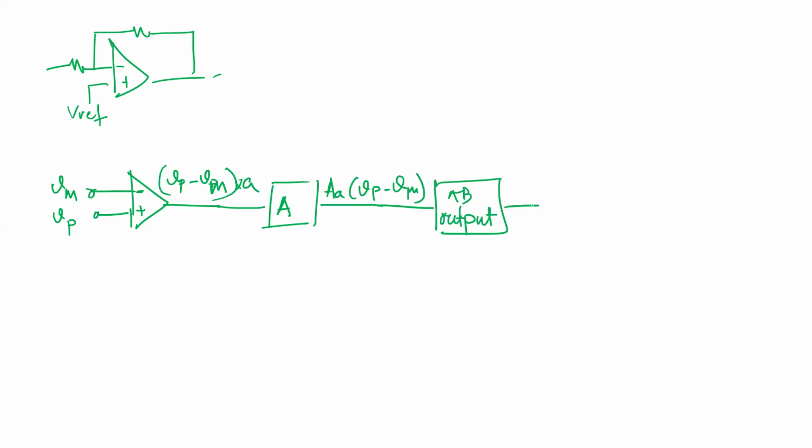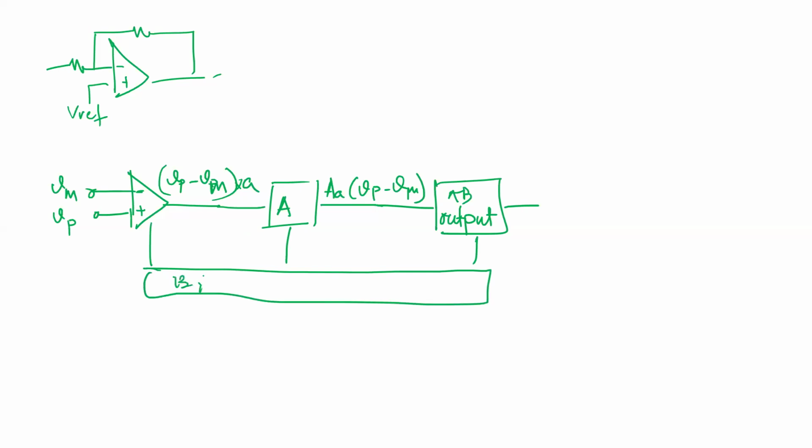And the job of the output stage is just impedance matching. So this guy has given you a lot of gain, but it can't provide much current. So if you have a really large load, like a really large resistance, then it will be able to provide it, but otherwise it cannot. So you add another stage where the gain is just 1, but it can provide current now at the output. Okay, so that's really the basic block diagram. And then you have all these bias currents you provide. So you have a biasing network, which in our case will be just, and this is your V out.